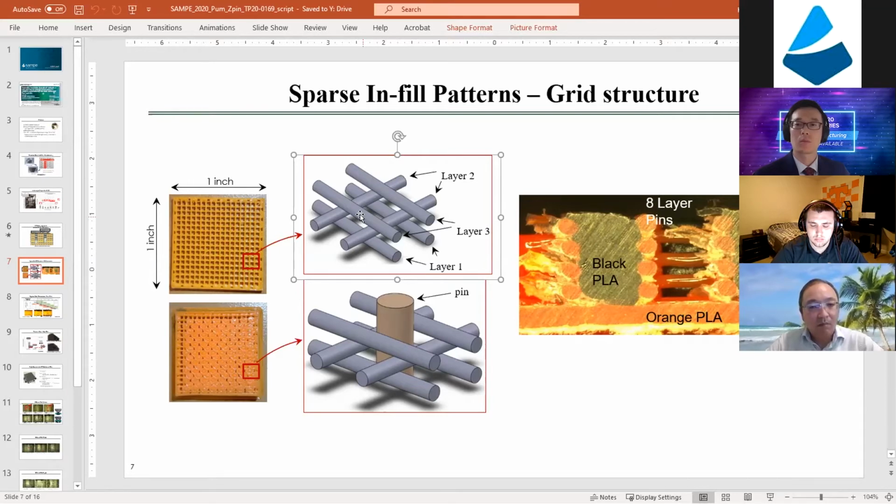Another way, if we have a completely solid part without any intentional holes, is that instead of going to a hole, because there is no hole in the part, we can deposit material on the side wall with a robotic arm. But in that case, the printer has to have a robotic arm instead of a 3-axis gantry system.